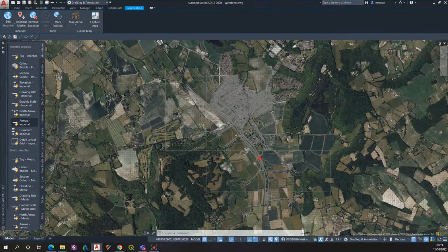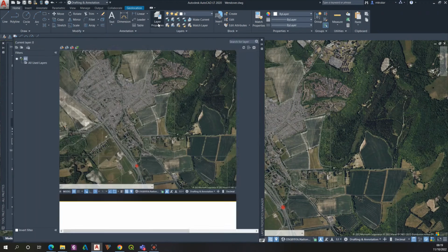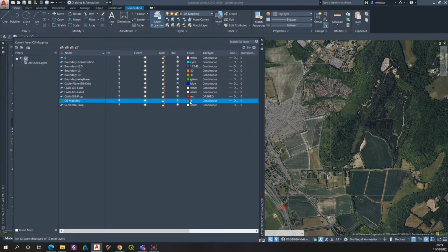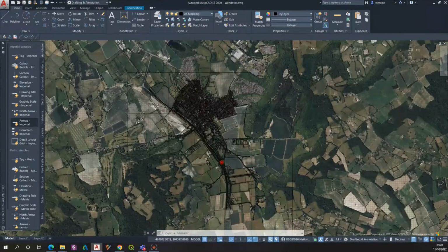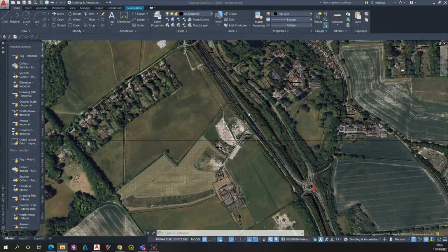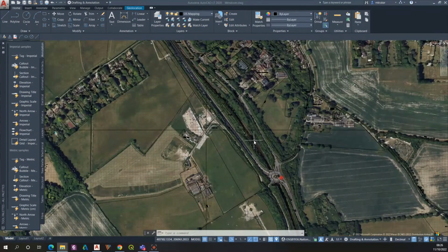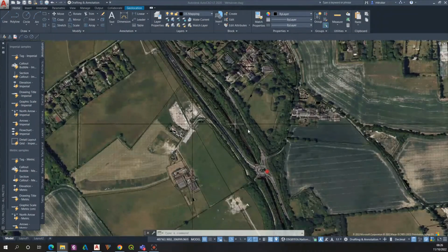clearly our drawing. Because the layer has gray coloration, we need to change this coloration to black. So in the layer properties, select the proper layer and change the color to black. Now we can clearly see our drawing, and we can also see all the mismatches which came out along the geolocation process. I mean mostly the shift discussed in my previous video. So let's go through these errors, fix them, and bring the geolocated drawing to functionality.